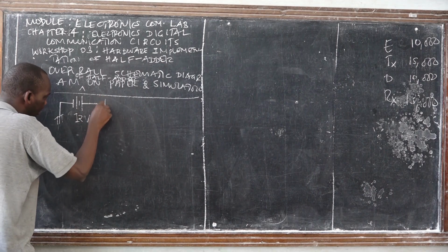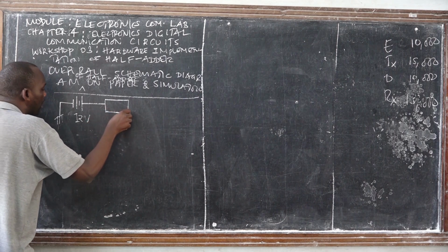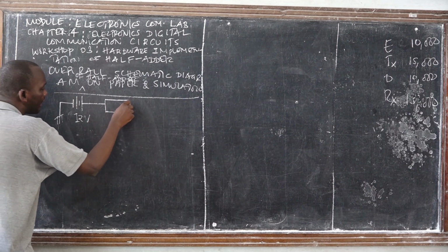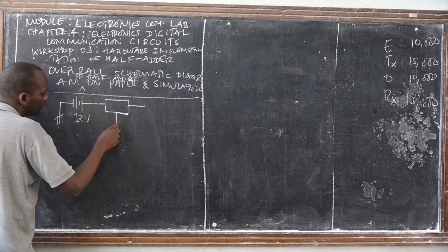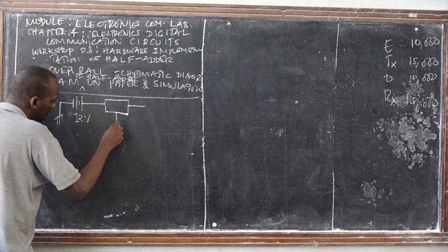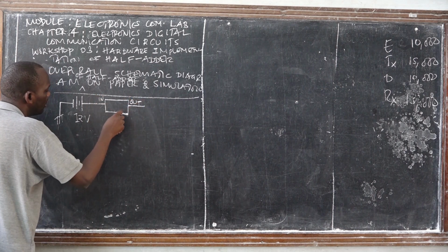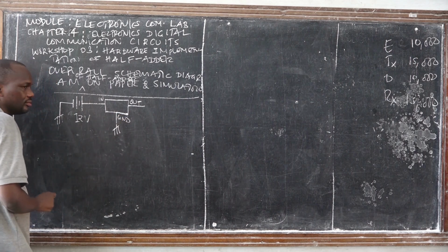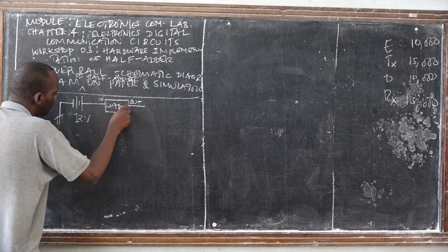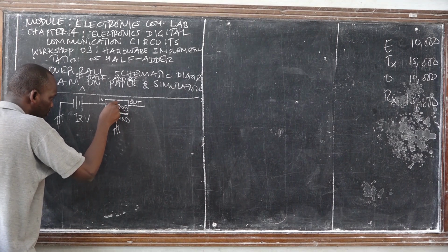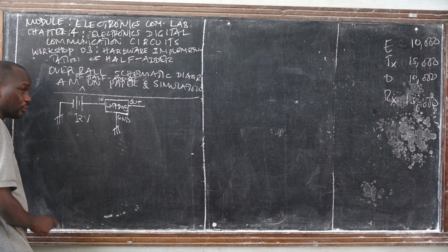And then we have to use this DC power supply unit, so you are going to use a voltage regulator. This is input, this is output, this is ground. This is the LM7805, but in Proteus it has been written as 7805.